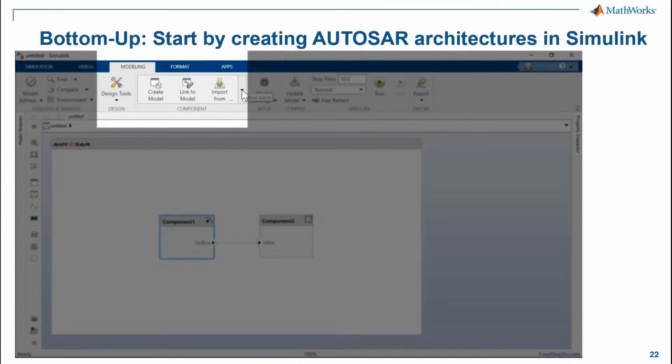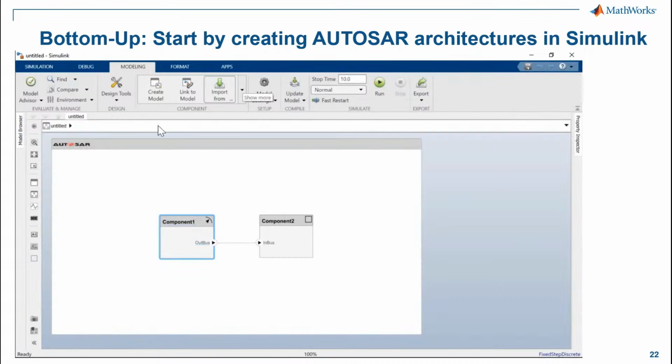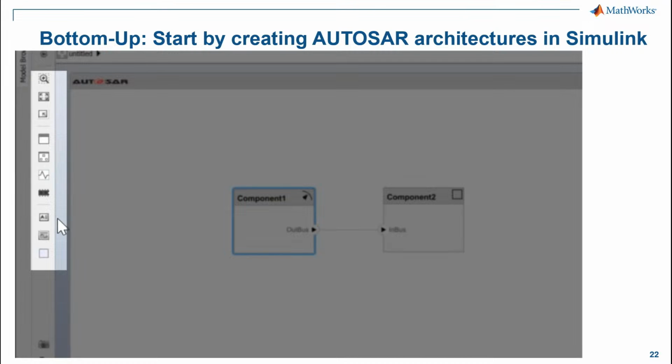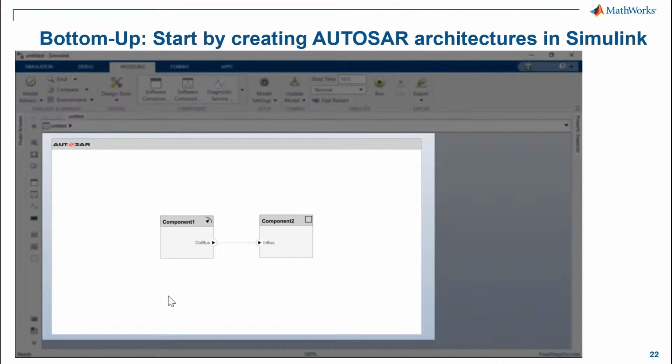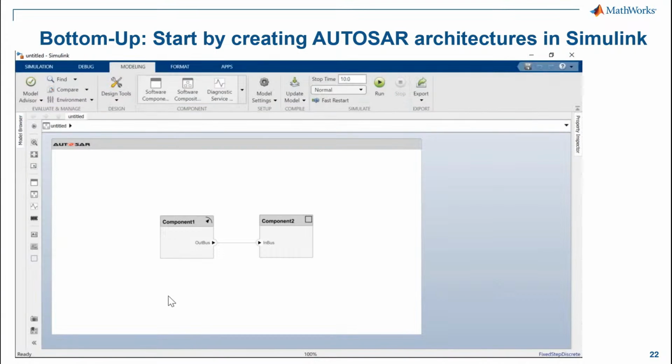And at the top, you can see options to import ARXML, and on the left side, you can drag and drop the components, compositions, and also the reference implementations for the basic software services. Okay, so now let me clear this default content from the window so that I can construct a new composition, since I already have a bunch of sensor component models. So I'm just going to flush this out and then create a subcomposition inside this composition template.